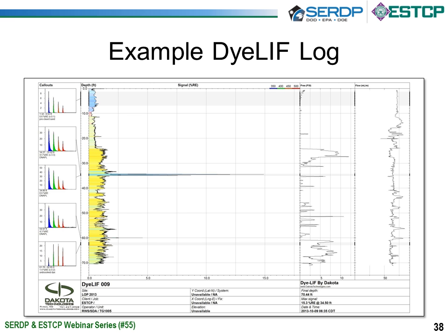And that's just an example log from that particular site showing where there is dye release, which is a good thing. You want to know that we're releasing dye. But then just a small thin layer of chlorinated solvent DNAPL, about 1.5 centimeters thick, that was clearly identified in that particular log and in several different logs.